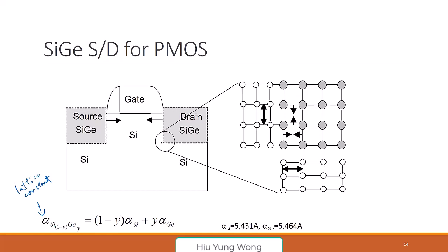But now you put it in silicon, what will happen? These are all kindergartner size. Now you try to fit all the adults in between, but you force them to have the same number. What will happen? Well, the kindergartners feel very relaxed because they are small size, but the adults are going to feel the compressive stress.